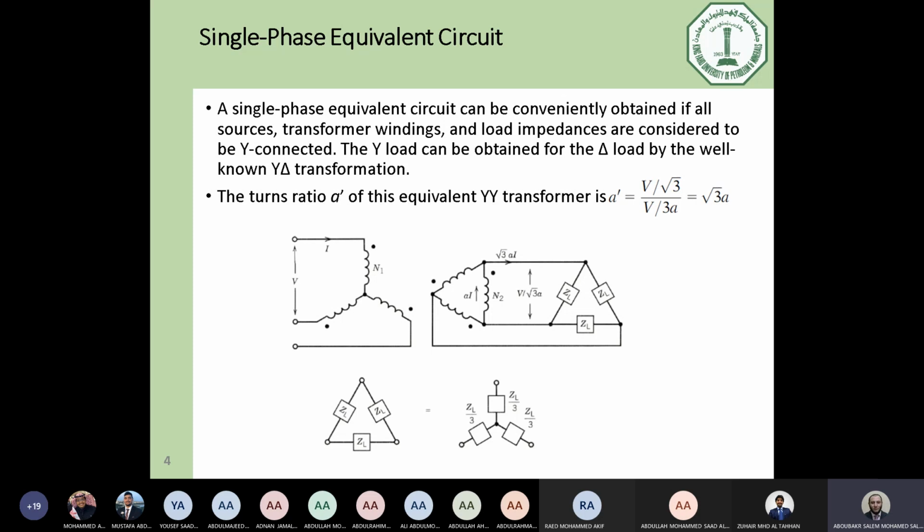However, for the approximation, we make some approximation in approximately equivalent circuit 1 and 2 in order to simplify the method or the circuit, in order to simplify the mathematical analysis, okay, to solve or analyze the problem. For three-phase, it will be more complex. So we also need to simplify to another circuit in order to make circuit analysis for the transformer, for the three-phase one. So simply, the method is called single-phase equivalent circuit.